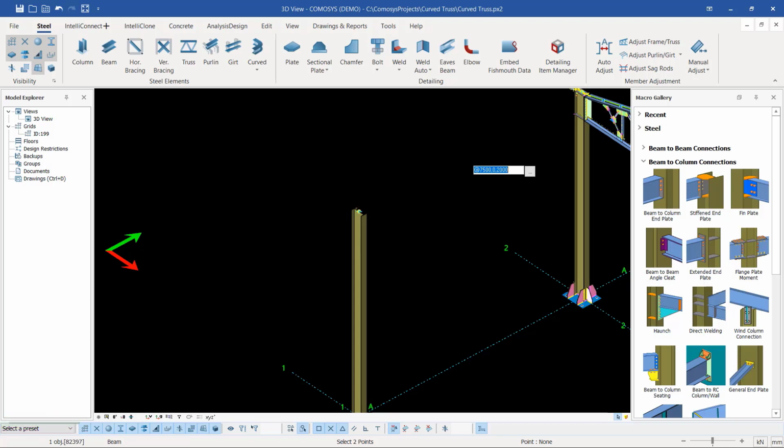because we have a span here, our span is 15. Now we want our rafter to terminate at the apex, which will be at the center of 15 meters. So this will be 7.5. So I'll press Shift Alt, then I feed in the half span of that 15 there, then a comma, then absolute 0, then a comma, then the apex height will be 2 meters, 2 meters from top of this particular column. So that height will be 2 meters.